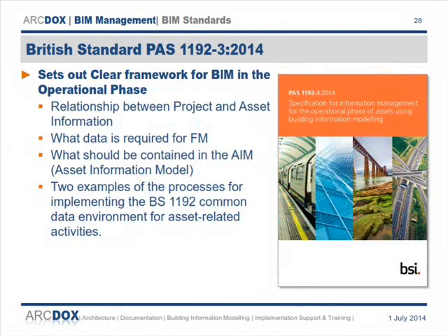PAS 1192 Part 3 is relatively new. It's only a couple of months old. And really it's to do with the FM stage of the project, how you manage the BIM information, or information generally, after you hand over, so in use. Yeah. So it sets out the relationship between the project model, or the project information, and the asset information. So the project information model and the asset information model.